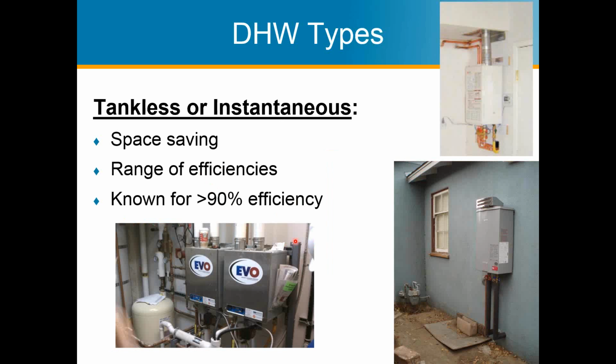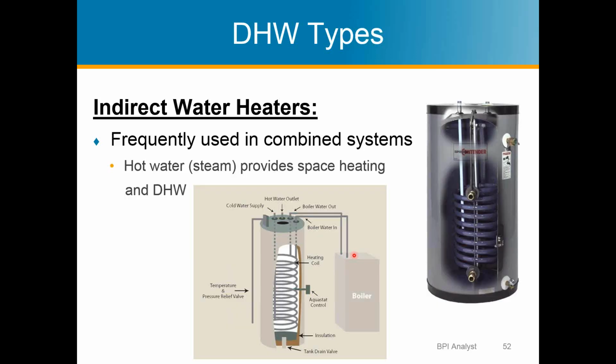And then there's the tankless or instantaneous. They're starting at 82% efficient and can go up to 98% efficient. One of the big advantages of these is not in saving energy, but being able to place it outside the building. So you get combustion outside the building, plus you free up storage areas inside the house. But a lot of times they do not save energy, even though they're more efficient. People just use them more. Nothing like running out of hot water to save energy.